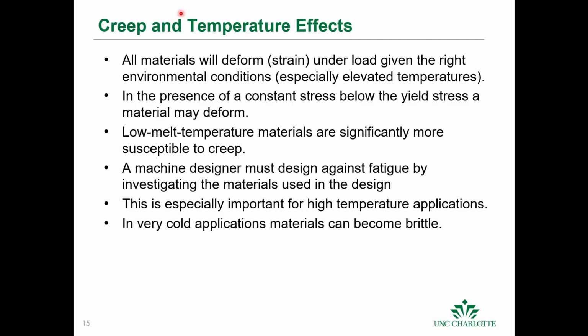If you have very cold applications, this is also very important, not for creep, but because it can change the material property. The material can behave as a brittle material. So you can get a very different failure mechanism if temperatures become extremely cold.